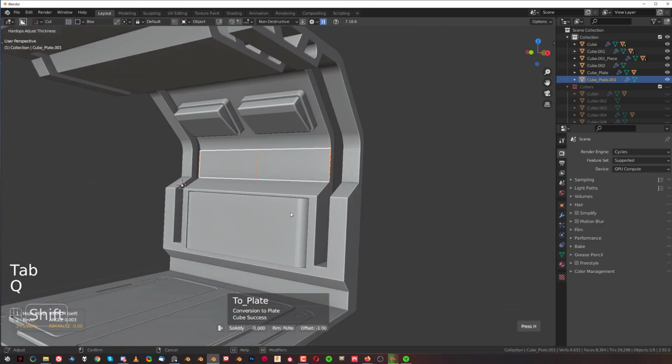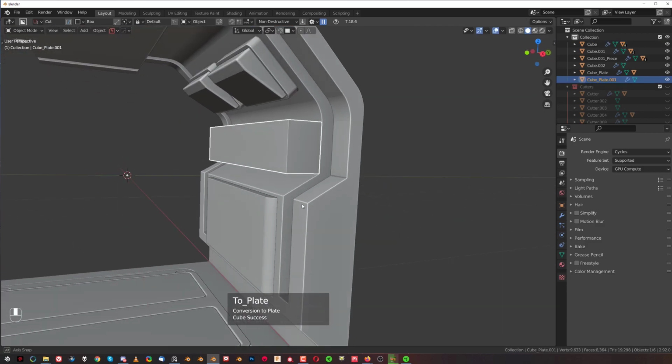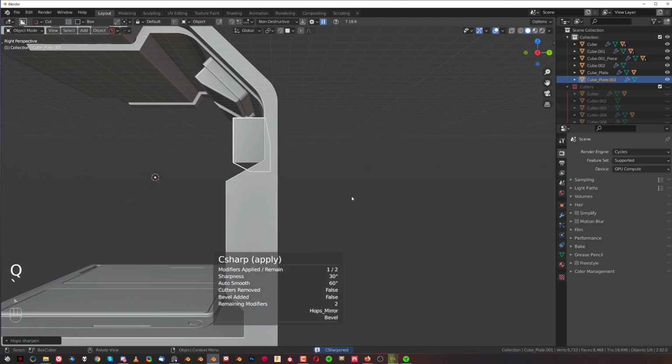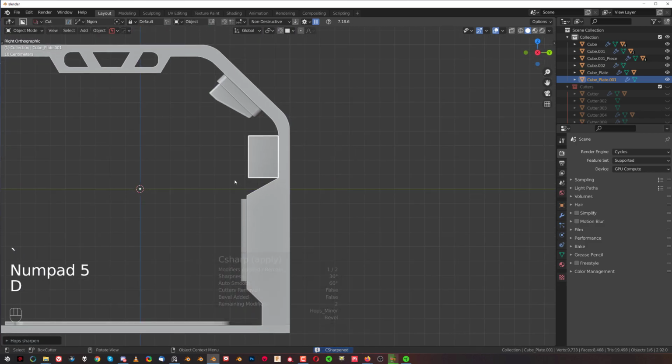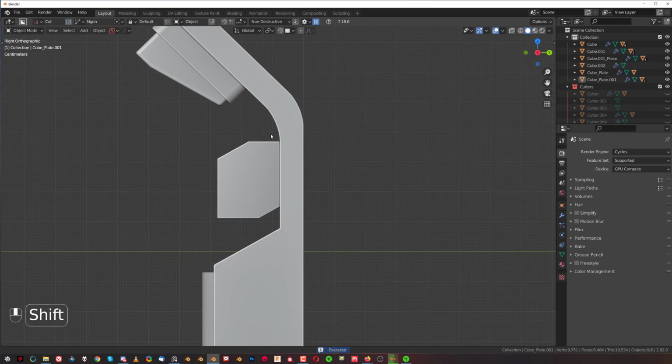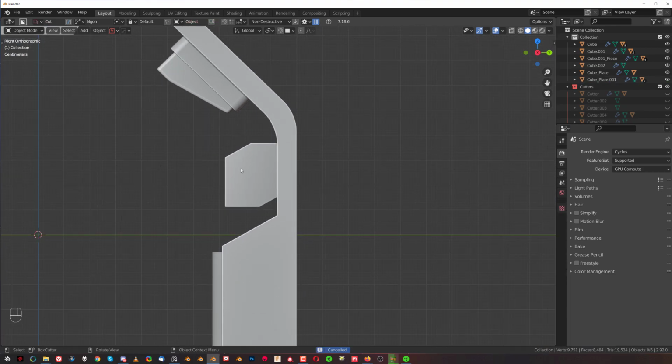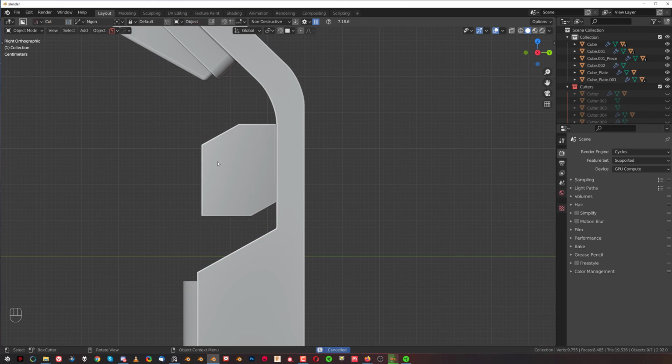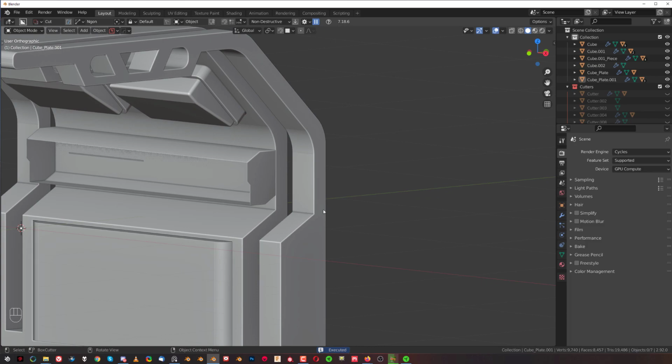So let's grab this one and shift curve extrude. That's what I meant. Let's sharpen this and let's see what we can do here. Let's grab an angle and start cutting this here in some kind of a cool fashion. Let's create something like this here. Come on. Oh, this is really annoying me. Let's go to input and right mouse button to cancel. It's my favorite behavior of Boxcutter. It's much faster to cut this way because I can immediately cancel my Boxcutter cut.